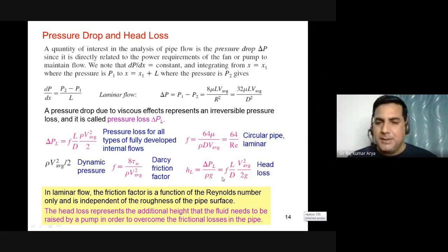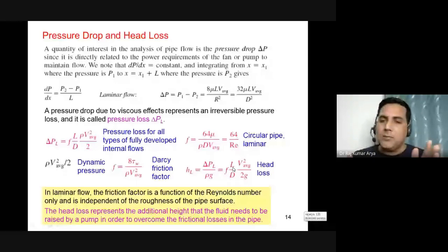So you know the friction factor by knowing the length of the pipe, diameter of the pipe, and velocity. You can calculate what should be the head losses only because of this flow, this velocity. You are not considering any roughness here. This is just only because of smooth pipe. Okay. Let's say for turbulence.